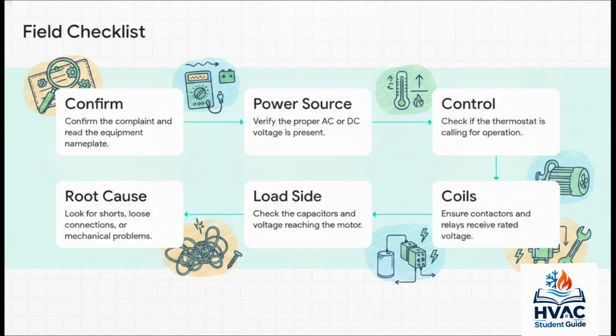And number 6, look for the root cause. Seriously, finding a loose wire or a low-voltage short is just as important as swapping a bad part, because if you don't fix the root cause, I guarantee that new part is going to fail too.